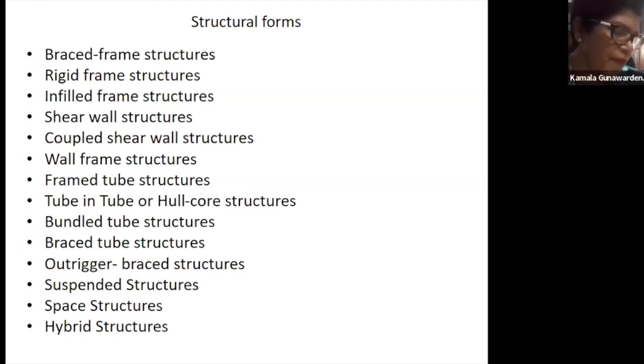What about the failure of flat slabs? The flat slabs can fail in shear, but you can have steel members like I-girders at the column, so that the shear failure of the flat slab can be prevented. So there are proprietary systems, you can use them. Shear failure of a slab is a problem, but it can be avoided with special, not reinforcement based, but steel member based systems.